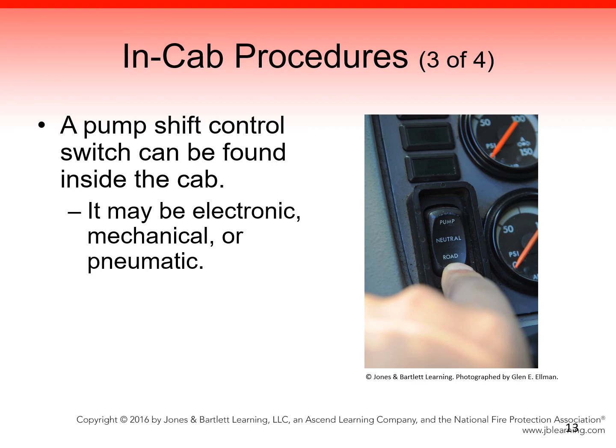A pump shift control switch can be found inside the cab. It may be electronic, mechanical, or pneumatic. Place your foot on the brake and move the pump switch from the road position to the pump position. It is important to pause in the neutral position between the road and pump positions, as this allows the fork in the transfer case to correctly move from the road to the pump position. If the transfer is made too quickly, the fork may not have had enough time to move over correctly. Look for the pump engaged indicator light to ensure that this switch has actually taken place.